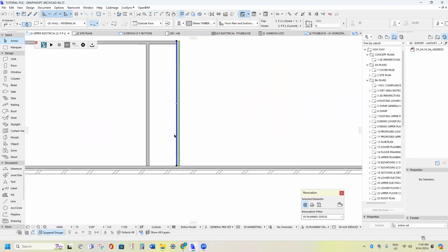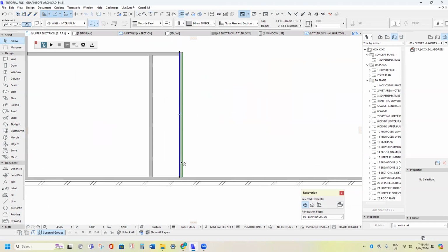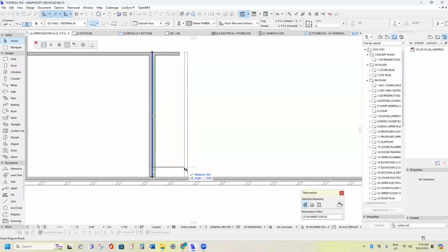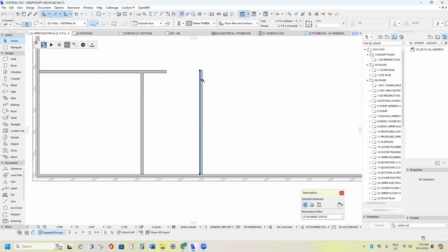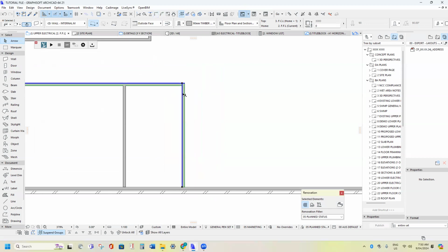Now that I know the master bedroom size, I can click on this wall, and we're going to make the ensuite and walk-in robe. So I'm going to bring that to here likewise, then Control D and press Shift and then R. And I'm going to make this go back, say 2 meters. Then I'm going to hold Shift while that one's highlighted, hold Shift and click on that, and then click on this one, and that intersects both walls.